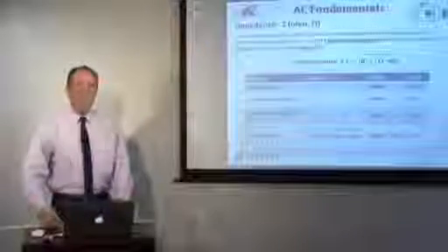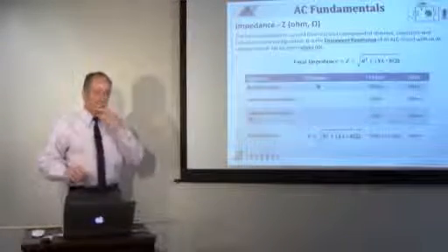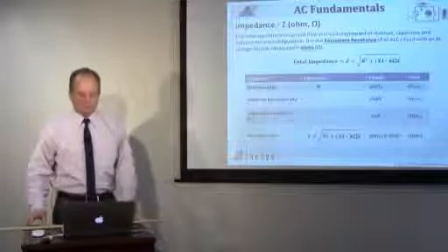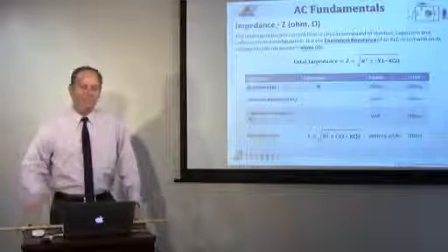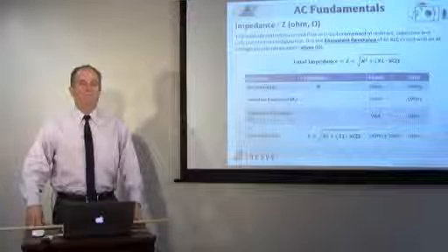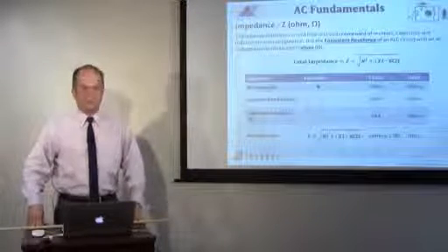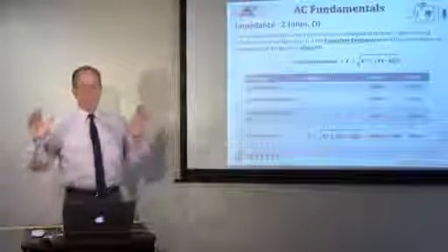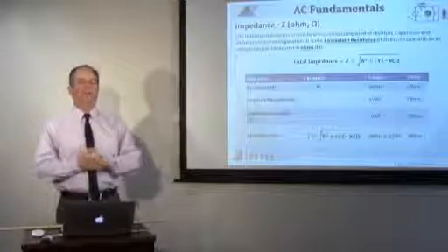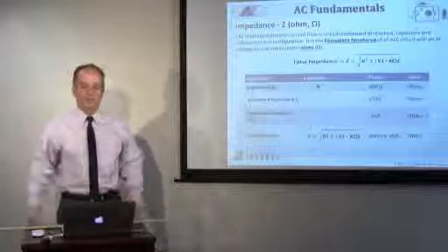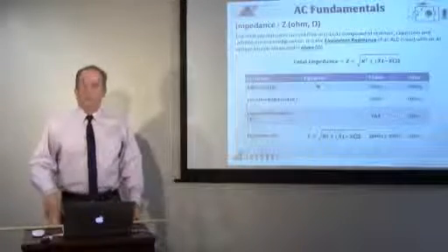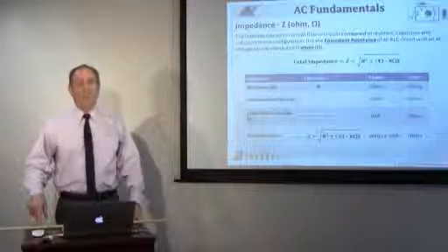And one thing very basic in AC that you should be aware of, actually this is what I did my master's thesis on, is that in a power system, you have both watts and VARs flowing. When you look at any power system diagram and you look at real-time operations, you have watts flowing and VARs flowing. And just like Kirchhoff said, the sum of the currents equals 0. Well, that's true with watts and it's true with VARs.